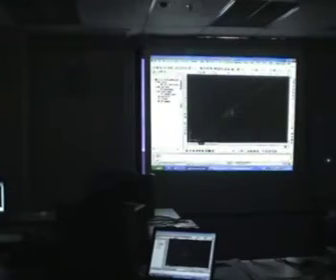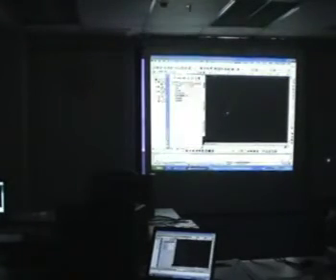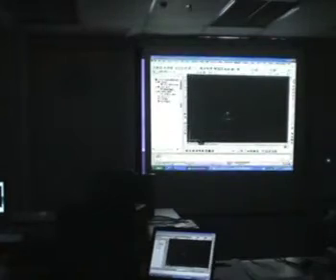And the text, right? Let's say you need to move the text. I just select this contour line. Just to point out to you, this is a civil contour object, not a polyline like in AutoCAD, not just a 3D line or anything like that. This is a contour object. You can see that the marker has also been selected together with the contour line.